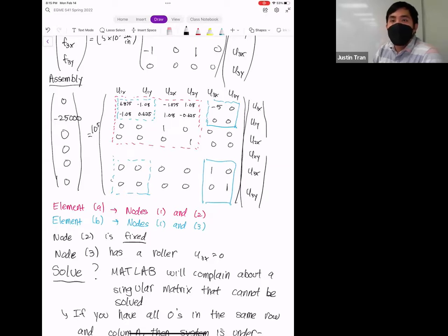Is this like the pen and paper equivalent of Ansys telling you to turn large deformations on? Well, Ansys will give you a solution, but it'll be inaccurate. Yeah, kind of. You can think of it like that. In this case you'd actually turn it off, and you'd add additional constraints to make it so that you don't have any large deformations.